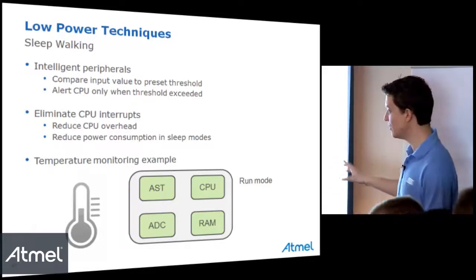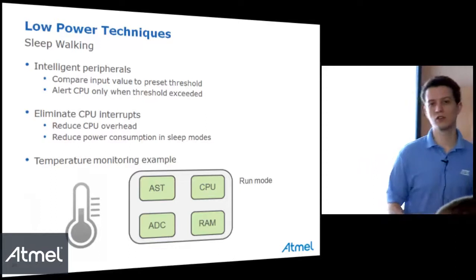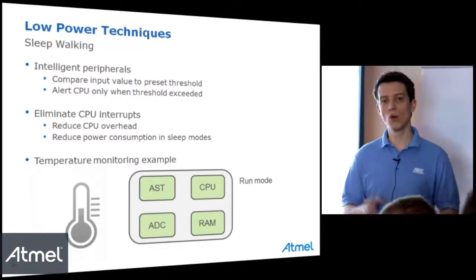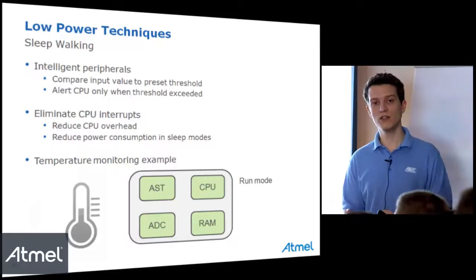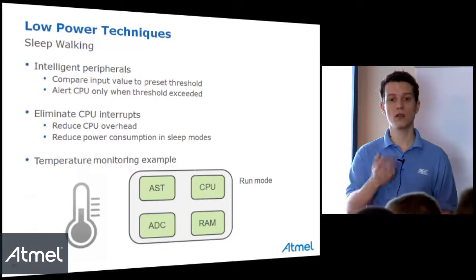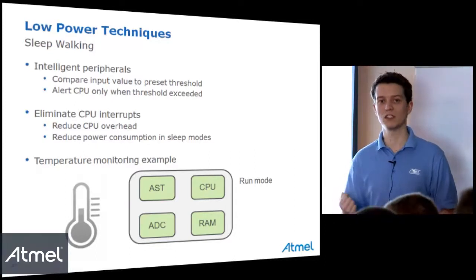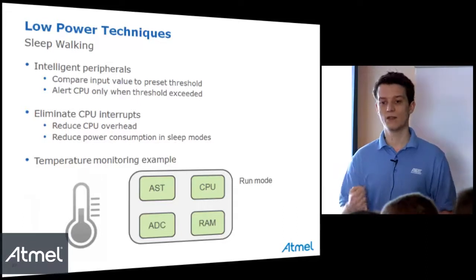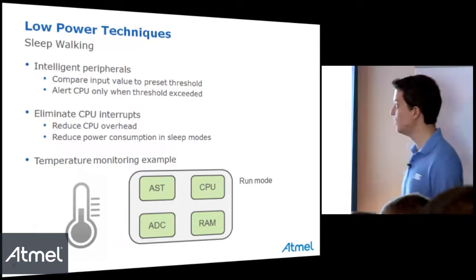So it means that even if the ADC clock, for example, is not enabled during low power mode, if the ADC receives an event and is activated, it will request its clock from the power manager. The power manager will automatically give its clock. Then it will use the clock for the conversion, then stop it without CPU usage. So this is also a key feature.